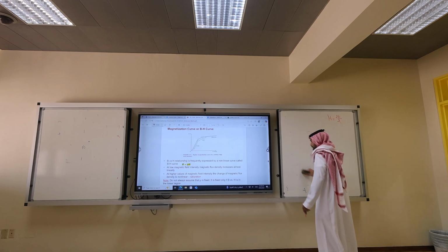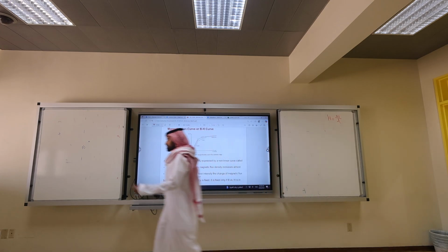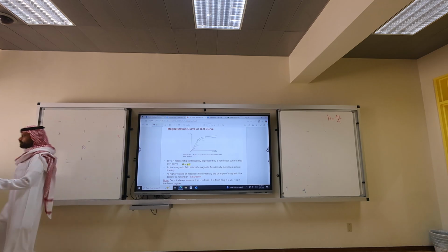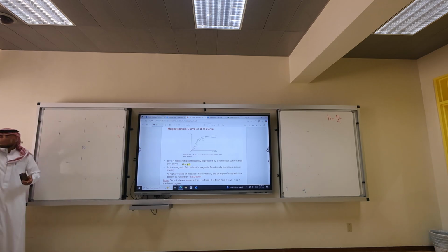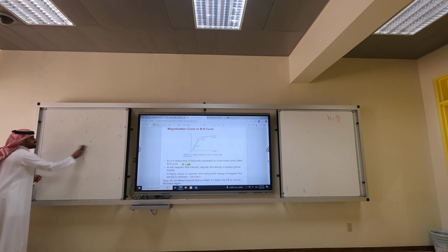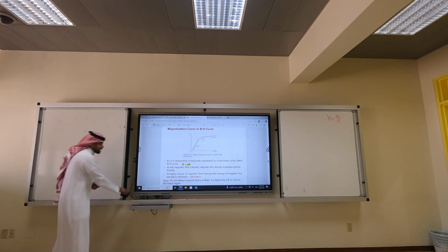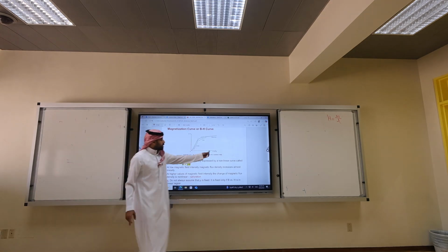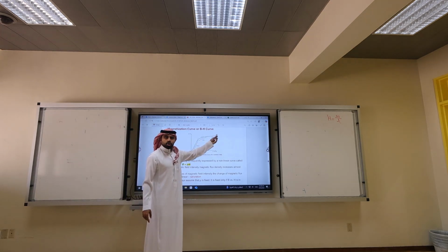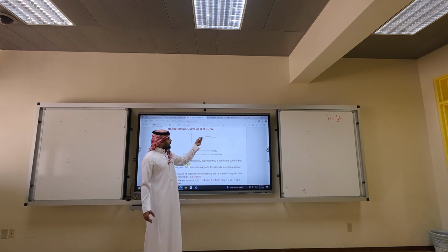No, life is not that easy. For some reason, the magnetic material has a saturation limit. You cannot exceed it, okay? Does it make sense to supply big H if I'm saturated? No. So we usually operate at the area called the knee.